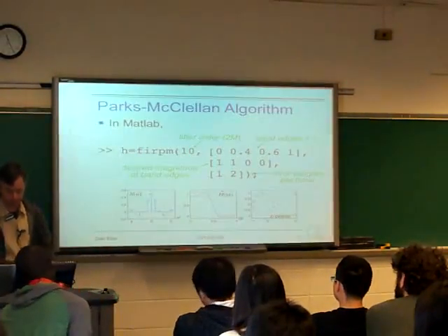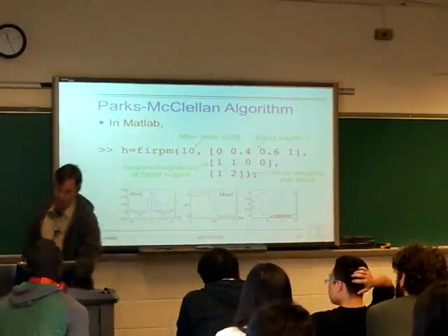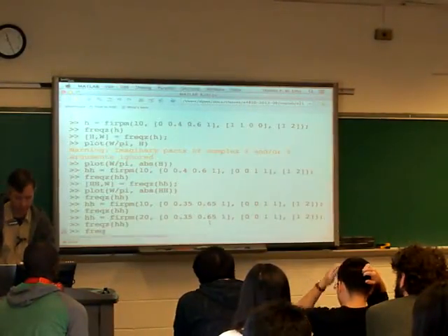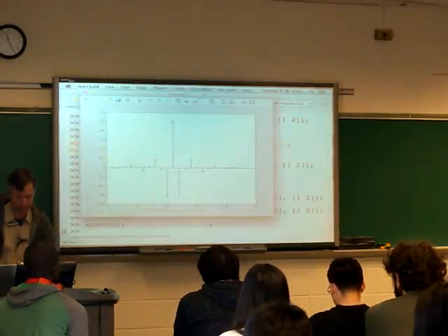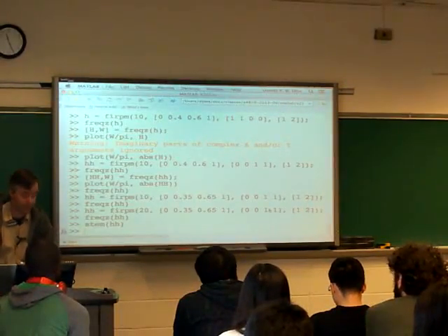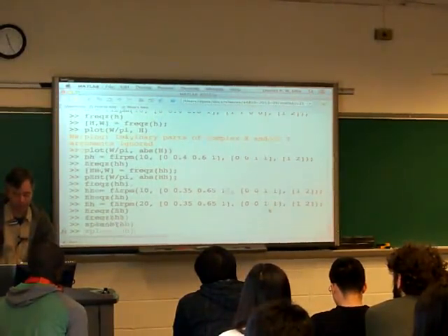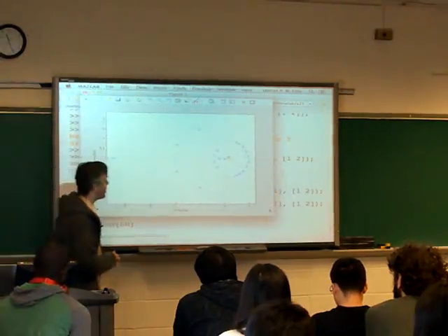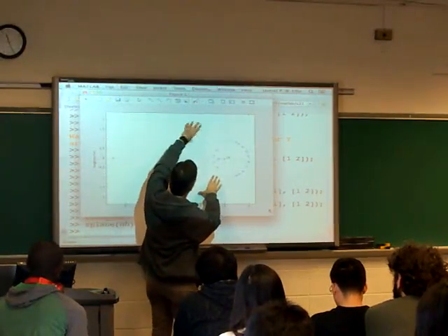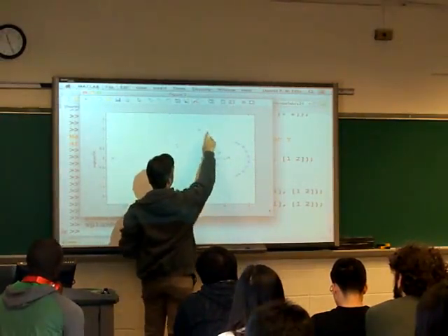So that's it. And here's the pole zero diagram. Remember what we're actually getting in MATLAB is just, if we stem H here, some impulse response. It's some set of symmetric things. It's a symmetric all-zero filter. So according to the things we learned about symmetric FIR filters, it has to have these zeros occurring in reciprocal conjugate constellations, right? So this is a high-pass filter.